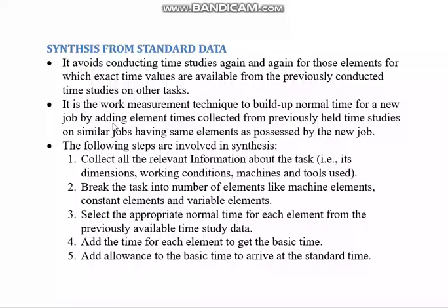Because this involves this task, and this task can be cut into so many time elements, and each element we know from the standard data. It takes so much time. So from the previously held time studies on similar jobs having the same elements as the new job, you will be able to estimate the normal time and thereby the standard time.